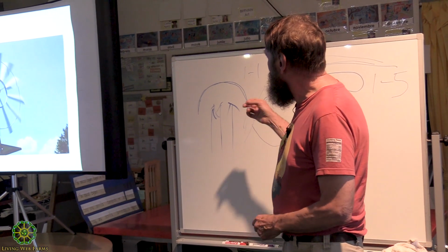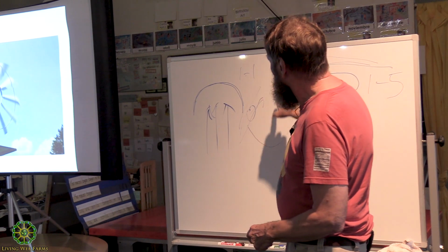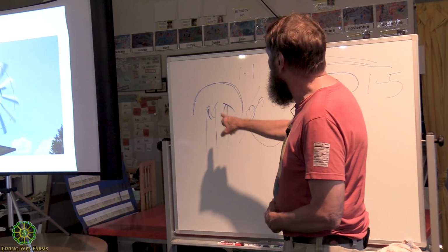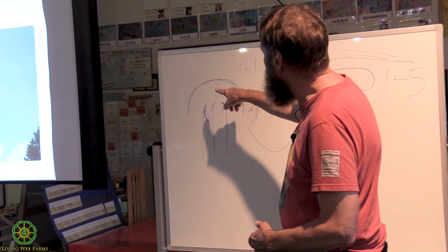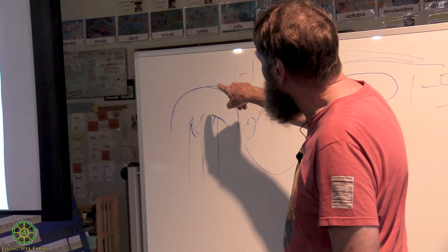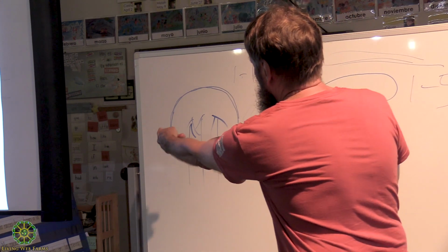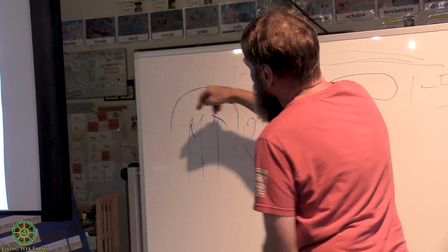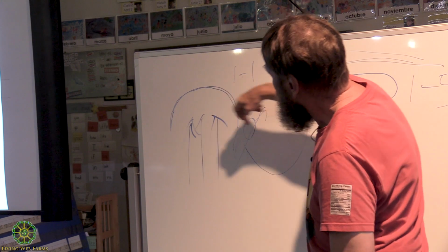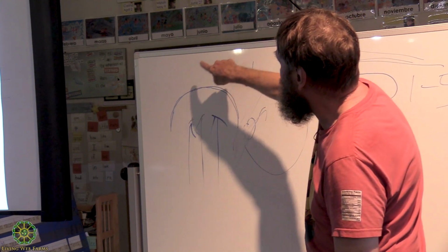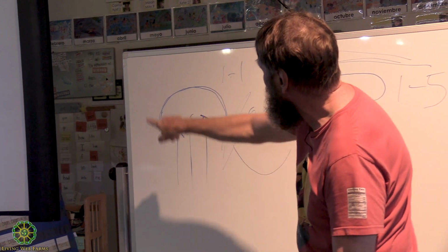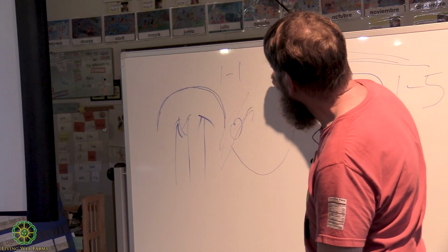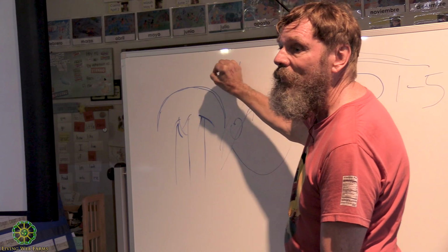On something like this, you can calculate how fast the shaft is going to turn by the fact of how many feet. If this is a 4 foot diameter, then 3.14, or pi, times that is going to be how many feet it's going to travel in one revolution.